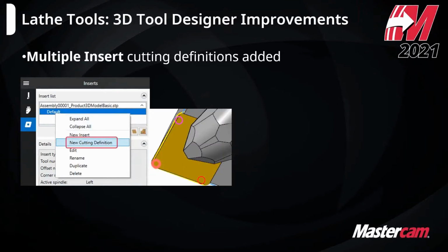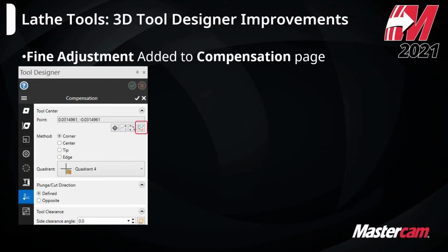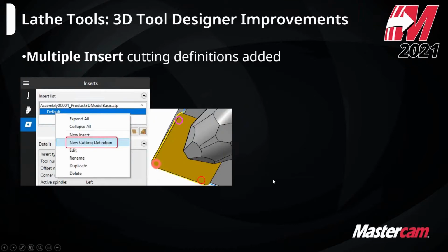And then we also now have multiple insert cutting definitions added. This is mainly to support what I'll talk about on my next slide. But there's a lot of lathe inserts out there now, especially on the prime tools, where it might be able to cut in multiple directions, or there's multiple points on a given insert that have the ability to cut. So you can have different definitions within the same tool now, as opposed to before, you would have to copy that tool and create a new compensation point and basically have a duplicate tool in there to accomplish the same task.